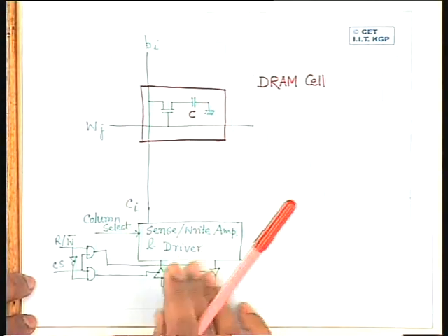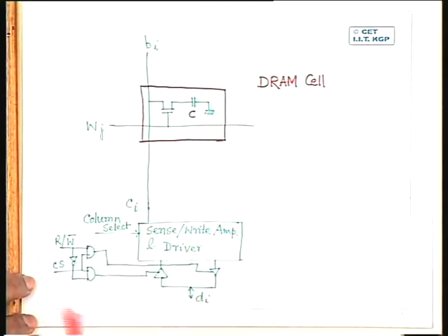Not only that, if I leave this RAM cell just like this, without any reading operation, even then the capacitor will be discharged because of leakage. So even if I don't read the DRAM location, I should refresh the DRAM at regular intervals of time. That means I have to have a mechanism by which the DRAMs can be refreshed at regular intervals of time, or it will be refreshed after every read operation. Okay. So details of all this DRAM architecture we'll see in the next day.